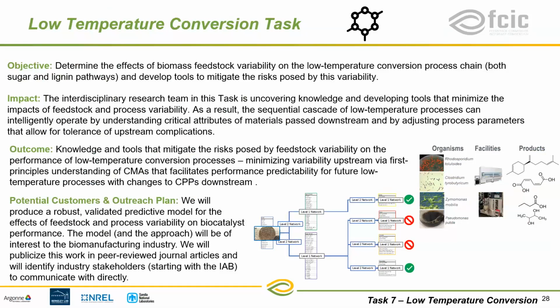Again, this is also a little bit different. We are doing the deacetylation mechanical refining followed by enzymatic hydrolysis to make a cellulosic sugar stream that is upgraded, and then the lignin-rich stream coming off the deacetylation is also upgraded. So what I'll do now is talk a little bit about the experimental data and then the modeling framework that it's going to be tossed into.